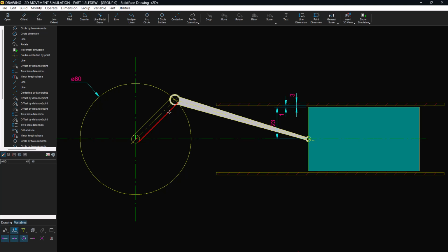In other words, for each processing of the list, the geometry will be deleted and then a new one built. Instead, when possible, choose to delete the commands directly in the list of commands. This action will also force you to delete all subsequent commands and return to the original stage at that point. The inconvenience is that we can only delete the commands with errors and the following ones. That's why it's important to test each stage of construction. Therefore, if errors occur, a minimum of commands will be deleted to return the geometry to the desired intent. In Part 2, we will show how to retrieve geometric information from geometry and use logical conditions to create test messages.